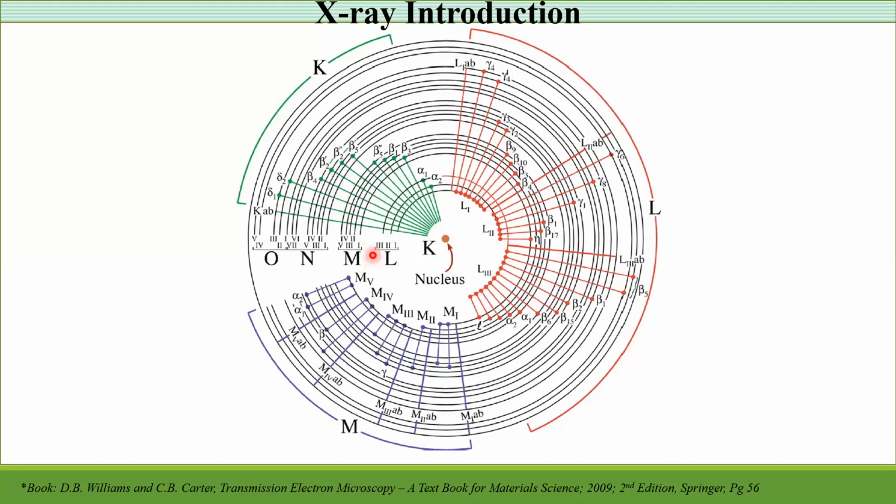But not in all SEMs, not in all TEMs. Try to remember that. So don't claim you have 50% of iron and 50% of chromium in your sample just because you have such a calculation from EDS. It will be wrong. In most of my review cases, I just wrote politely not to mention that.